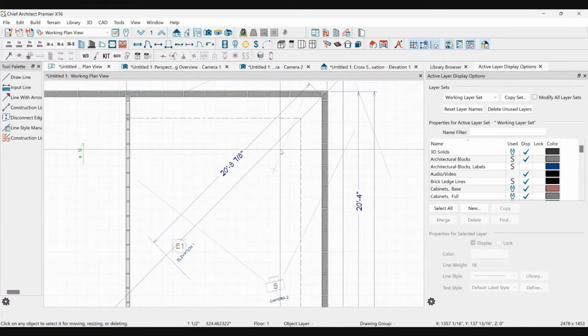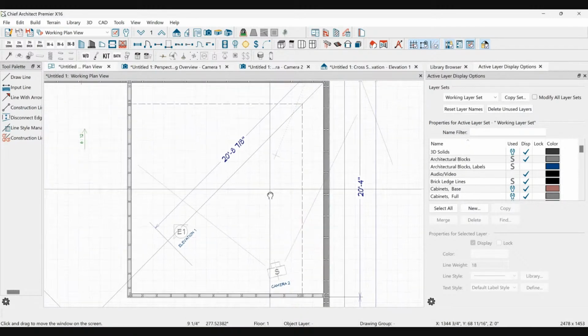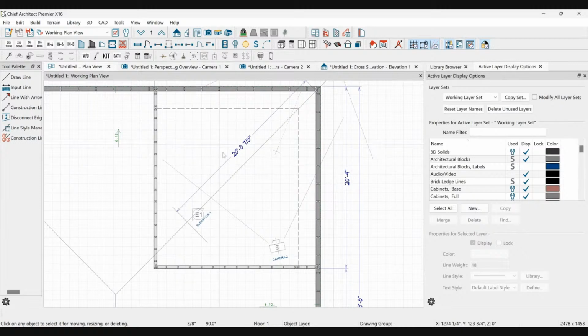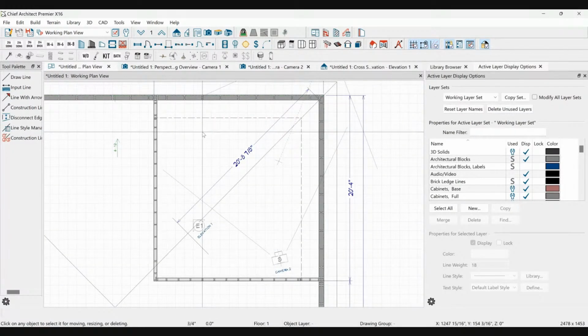You could also put one brace down, if you really wanted to avoid putting a funky, expensive LVL hip here, you could brace down to each ceiling joist and basically say, all right, fine, each ceiling joist is going to be a 2x12, and I'm going to put a little bit of weight on each ceiling joist. And now you've basically spread the load out over a whole bunch of different items. And yeah, that's probably cool. And as an engineer, that would probably work out just fine. So this is where that happens.